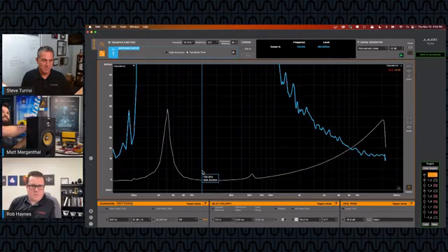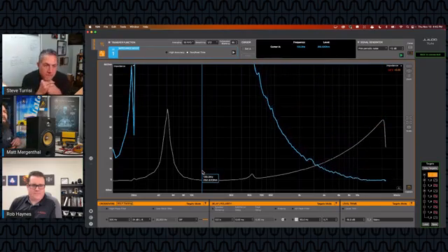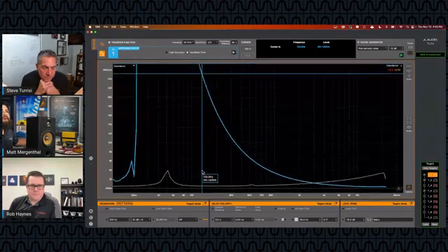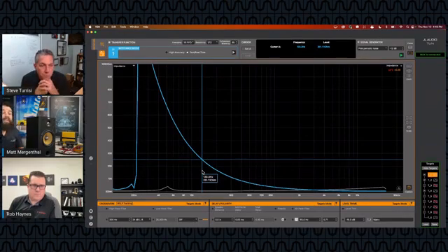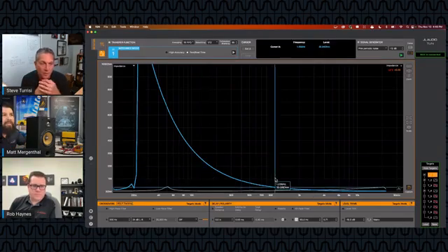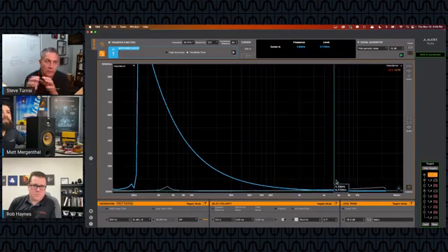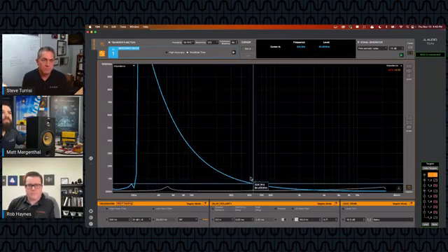Hold on a second. I think I got some extra resistance in there. Wow, that's a big one. Well, you would expect that on a tweeter, that it just goes off the chart at low frequency. Yeah, that's very true. I wonder, Matt, if there's a capacitor inside the enclosure on that tweeter too. I believe there is. So that would add even more on that rise there. Yep, it would be like a sharp high pass filter causing that.